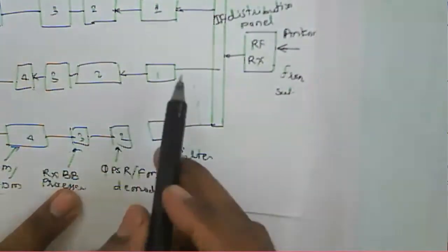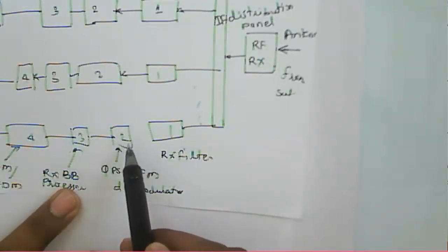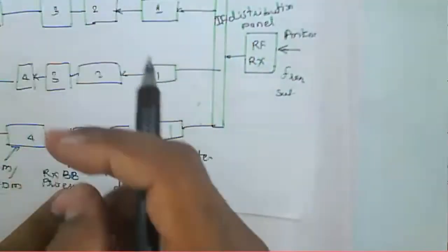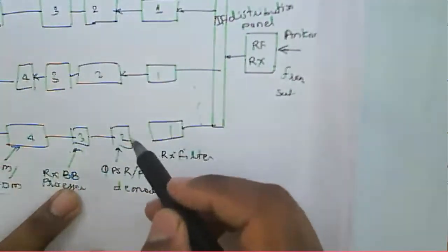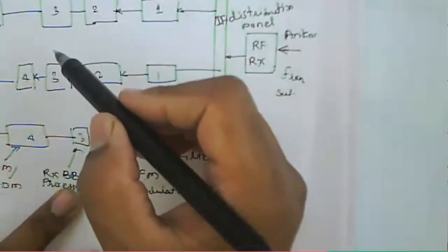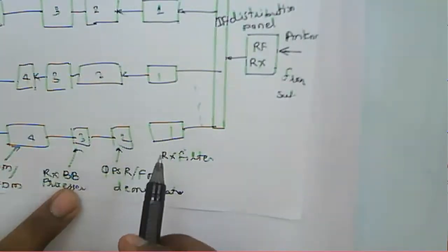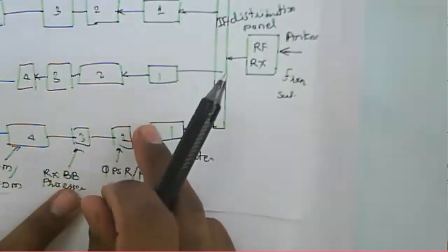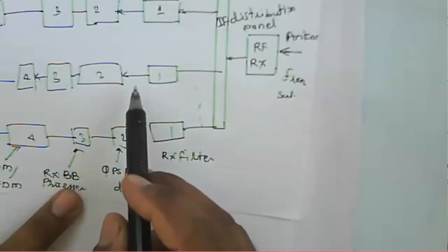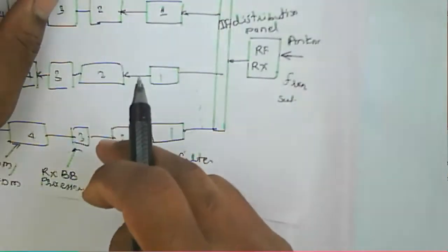Each carrier has different demodulation techniques, whether analog channels or digital channels. So the appropriate demodulator is to be used: an FM demodulator for analog channels and a QPSK demodulator for the digital signal. After demultiplexing of the received signal, the demultiplexer's role is to separate the voice channels.